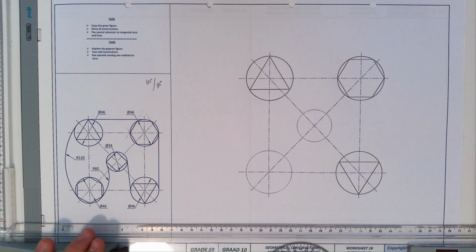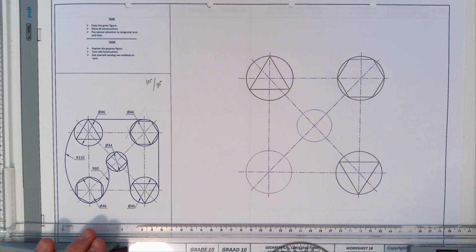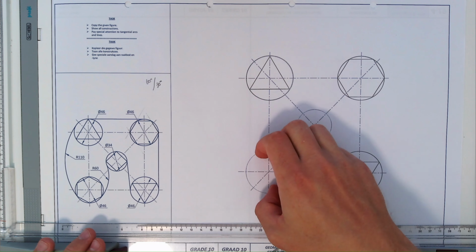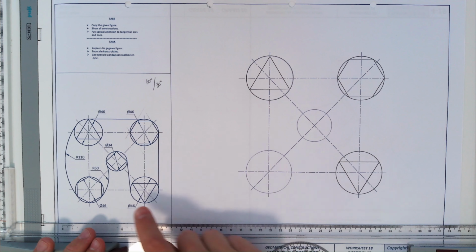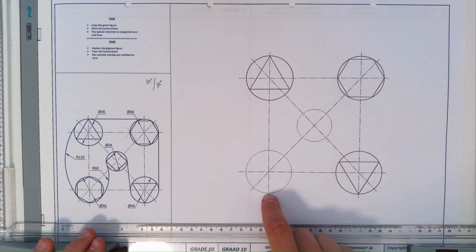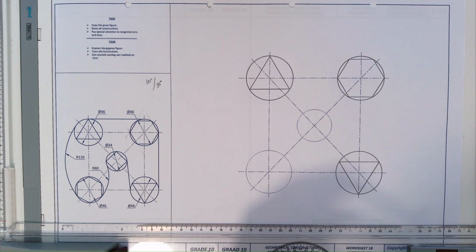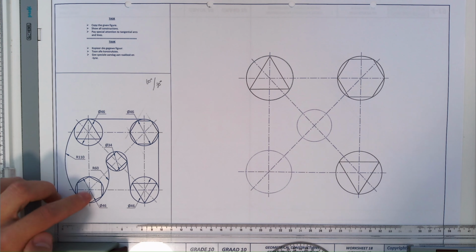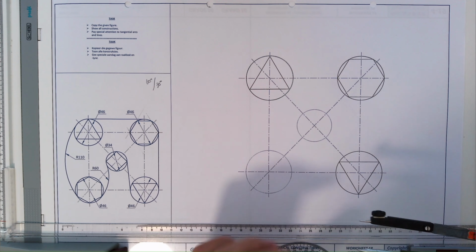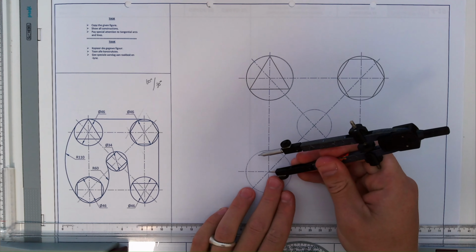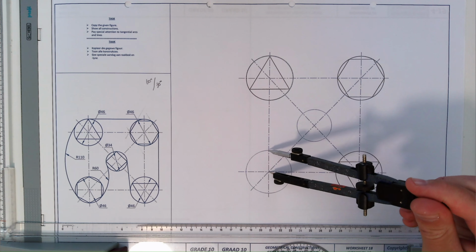Happy with that. Now we are going to do this hexagon. This hexagon is rotated so that the point is pivoting on this end. You can see that the point is touching this part of the center line now. But I want to show you a different way of constructing this. Because the point is connecting on that point and that point, what you will do is take your compass. You are going to set it to that radius.